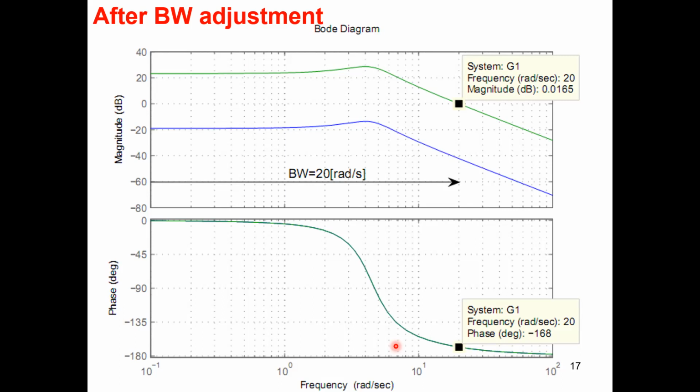That is not good. Now there can be various combinations of these things. You are feeding back a 180-degree out of phase signal, but the gain is not 1, more than 1 or less than 1. More than 1 is again a disaster. Less than 1 can be okay, because in successive loops, it will die out.